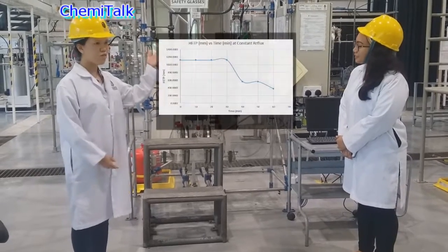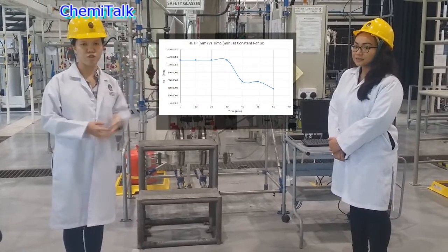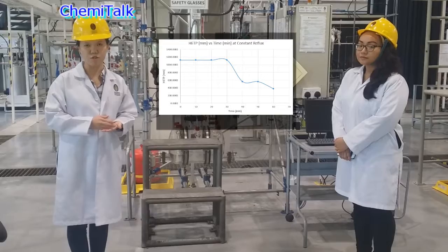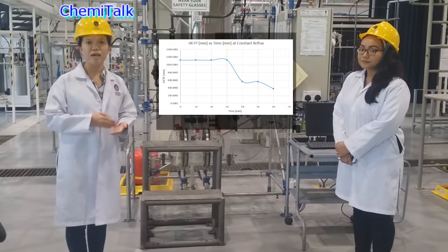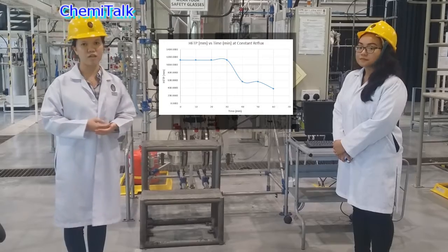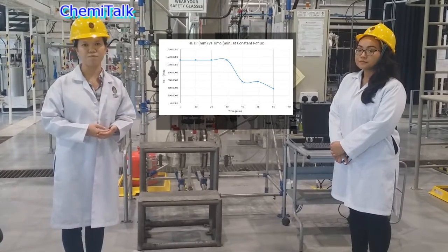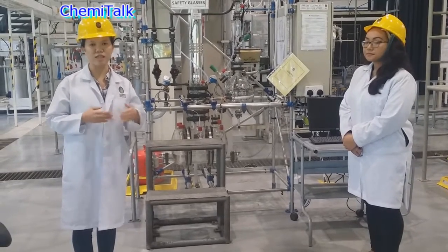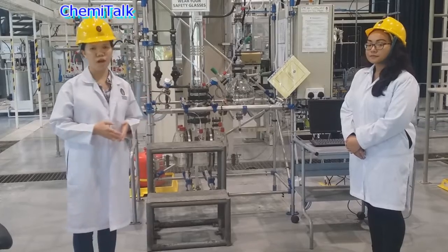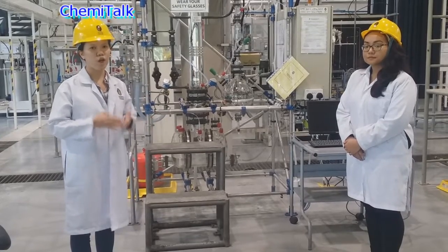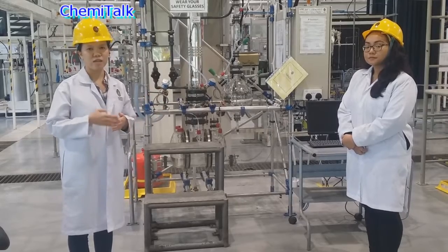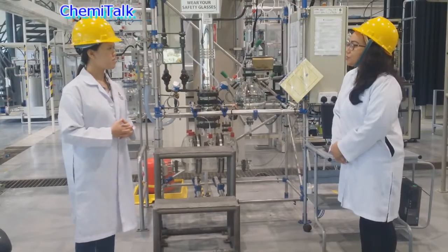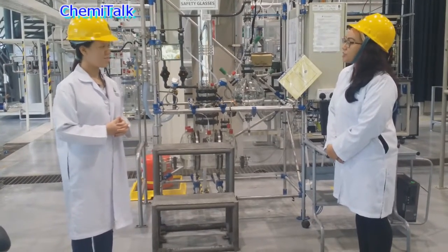Okay, from the graph, the HETP is showing a decreasing trend. From our research, we know that the number of theoretical stages is inversely proportional to the HETP. Thus, in this experiment, the number of theoretical stages is increasing with time. Theoretically, lower HETP and higher number of theoretical stages indicate that the distillation column will have a higher efficiency. Thus, we can conclude that the longer the time, the higher the efficiency of the batch pack distillation column. So do you have anything to add on regarding the results of experiment 2?